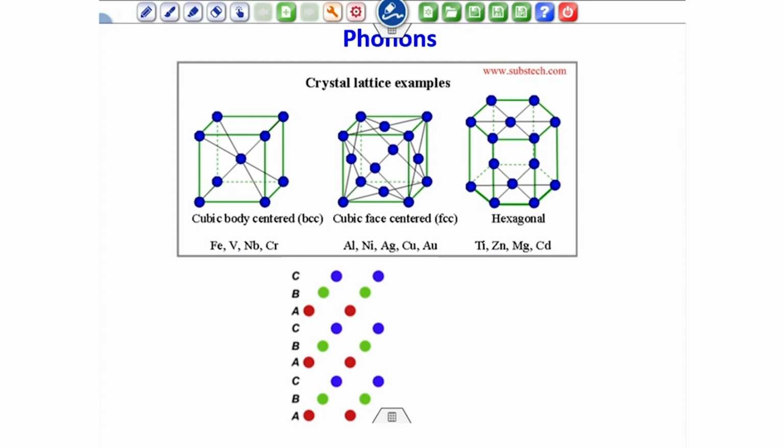In a standard material like FCC, atoms are arranged in a chain, right? These ABC layers. Now, these atoms can be considered to be connected by springs. As they are connected by springs, during heating of the material the atoms will vibrate about their mean or equilibrium positions. As they vibrate from both directions, one atom can push the other atom, or pull the other atom in the neighborhood, and this can lead to a traveling wave, and that is what is known as a phonon.